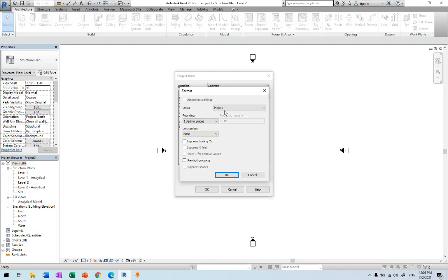0.01 meter, it means what? It will be 1 centimeter. If I need millimeter precision, I can go here, or it's better to change this one to millimeter in that case and make the precision 0. You don't need to go beyond millimeter here. 1 millimeter is enough for your precision. Whatever you're doing, whatever things you have, the precision is basically 1 millimeter.